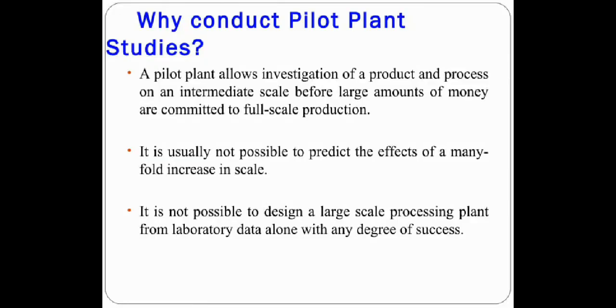Then why do we conduct pilot plant scale up studies? What is the need? A pilot plant allows investigation of a product and process on an intermediate scale before large amounts of money are committed to full scale production. It is usually not possible to predict the effects of a manifold increase in scale. It is not possible to design a large scale processing plant from laboratory data with any degree of success.